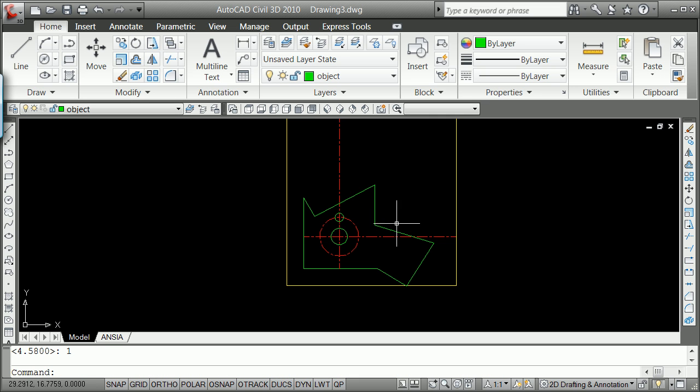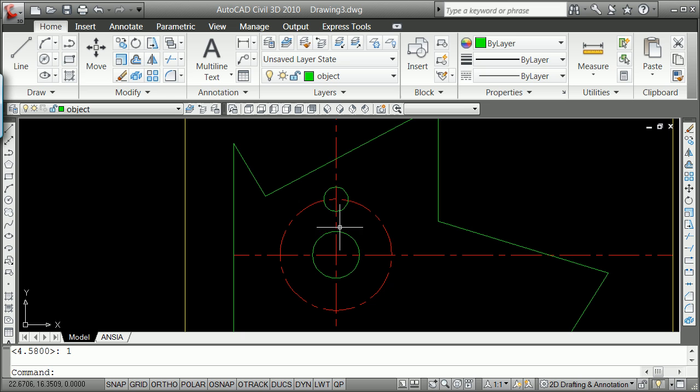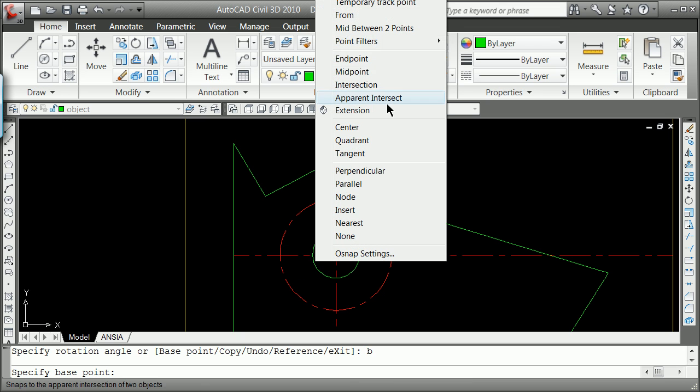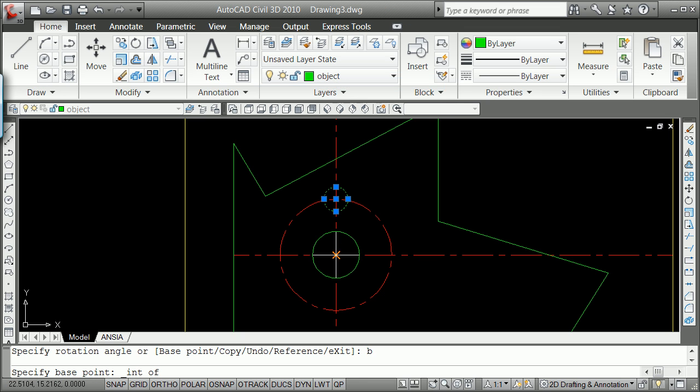And finally, keeping on this theme, we can go and we're going to left click, right, and then left click, spacebar, spacebar. We want to rotate, but we want to change B, the base point. The new base point is going to be the intersection of here. And you're going to change it a rotation angle of 60 degrees. And I forgot to do the copy, but I'm out of time.